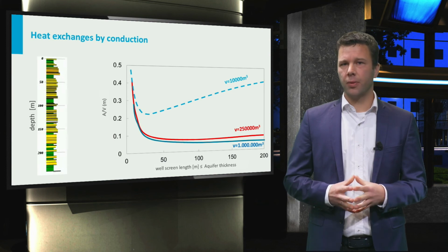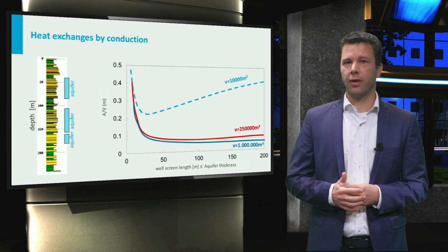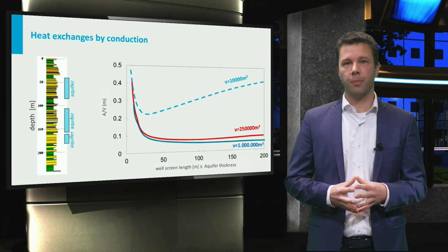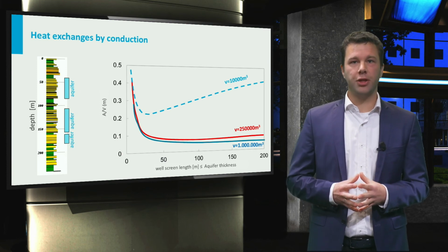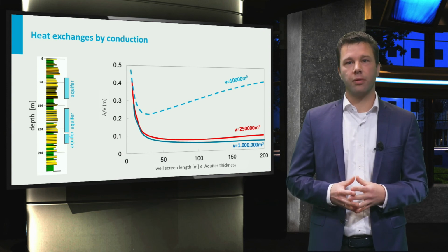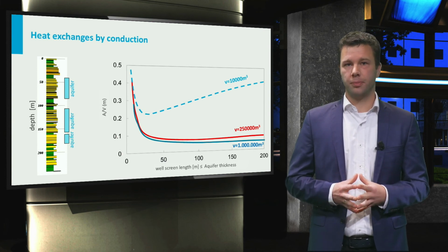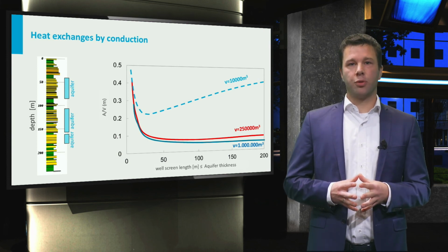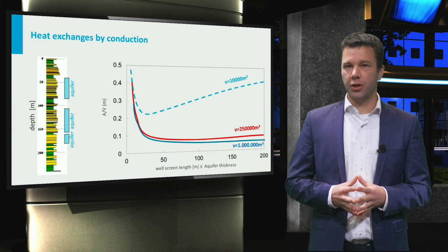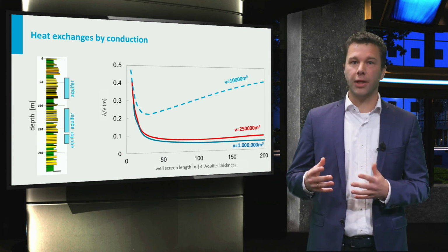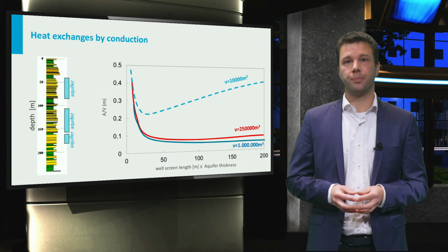In practice, we cannot freely choose the well screen length, as aquifer thickness varies depending on local geologic conditions. You can use this relation between aquifer thickness and losses to identify the most suitable aquifer for any required storage volume. Remember that the examples provided here refer to simple situations where, for instance, no regional groundwater flow or density difference due to high storage temperatures occur.